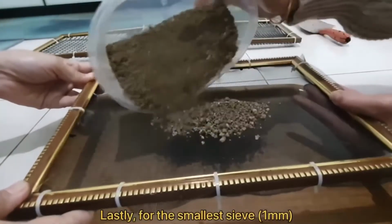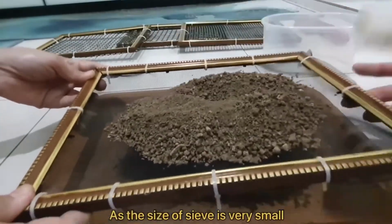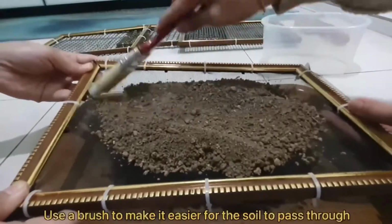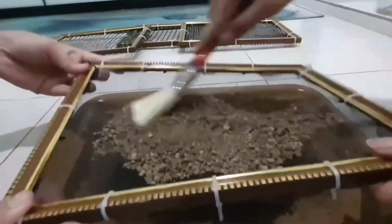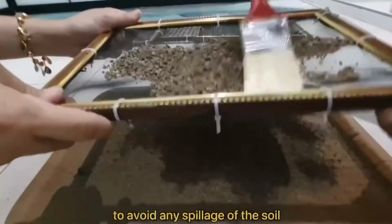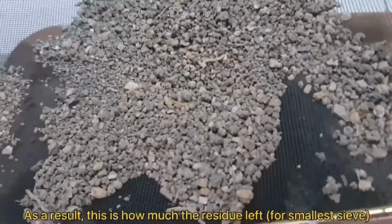Lastly, for the smallest sieve, the procedure needs to be done carefully as the size of the sieve is very small. Use a brush to make it easier for the soil to pass through and shake it a little bit. This must be done carefully to avoid any spillage of the soil. As a result, this is how much residue is left, and this is how the soil retained looks like.